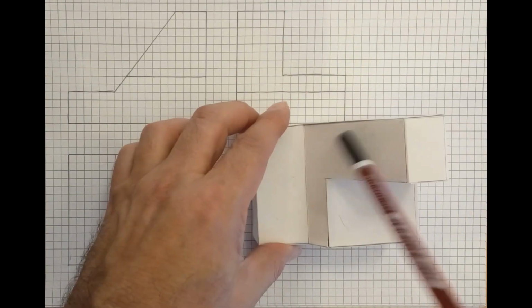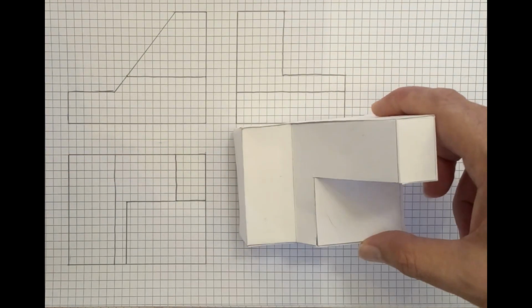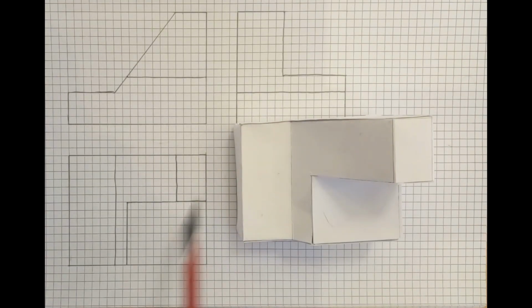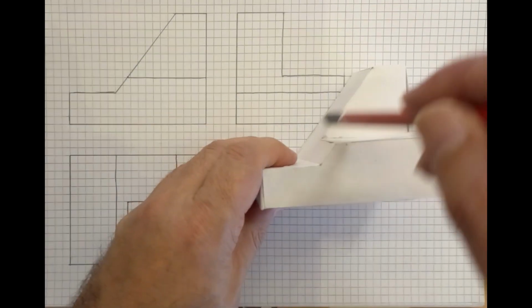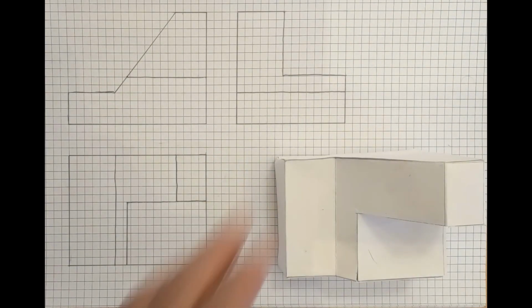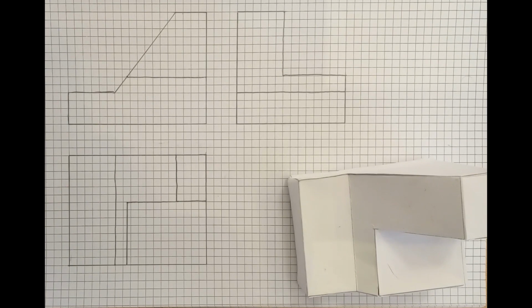For this surface, because it is inclined, in the side view and the top view, my side is inclined to this surface, so it will appear like this, an L shape, but the dimension is different. Okay? While in the front view, my side is parallel to this surface, so it will appear as a line like this. So we can review each surface in the part to see if it is represented in our three views or not, to see if we missed something or we did something wrong. Hopefully you understand and you can draw three views of any part by yourself.